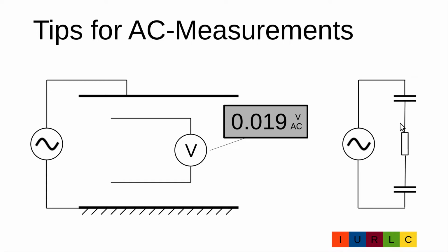Due to the high resistance of the internal resistor, the current through the tiny capacitor could already cause a significant voltage, which is about some tens of millivolts, in some cases even 100 millivolts, depending how close the measurement wires are to the power supply lines. When we make a short of the measurement lines, the display goes down to 1 or 2 at the last digit, which is the basic error of the AC voltage measurement.